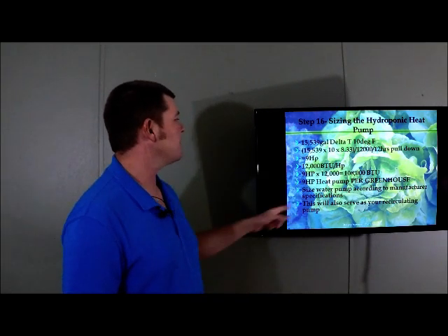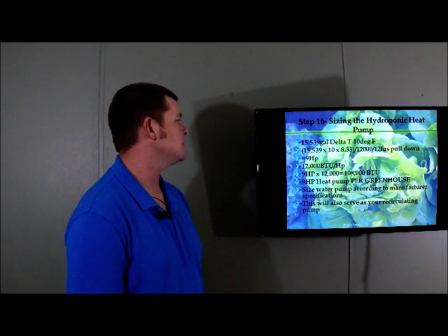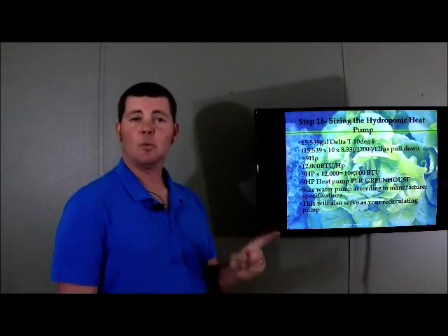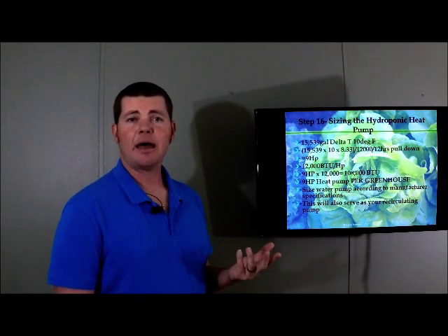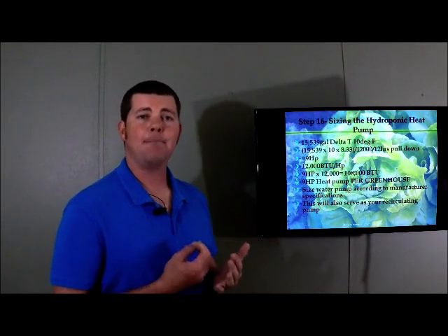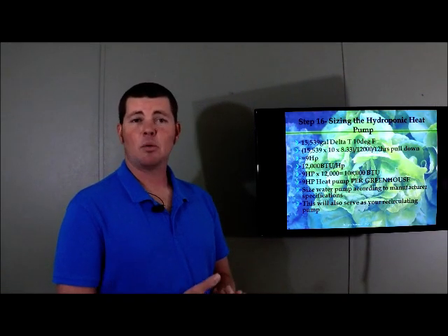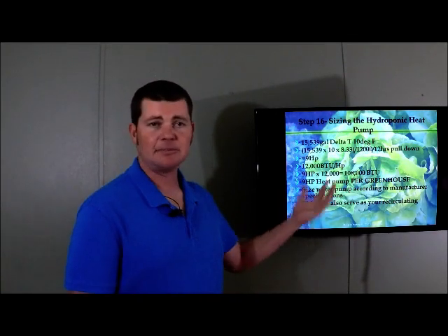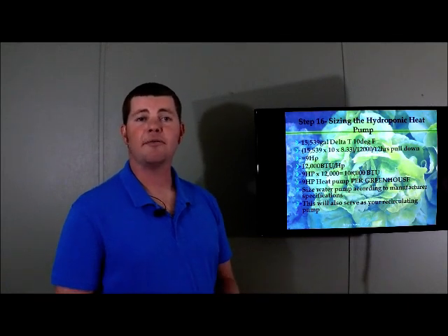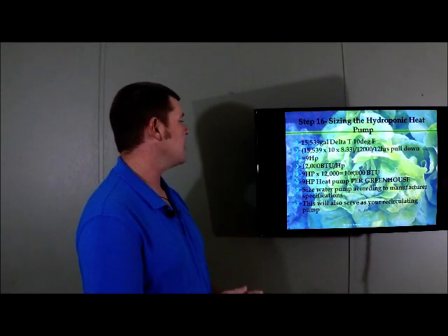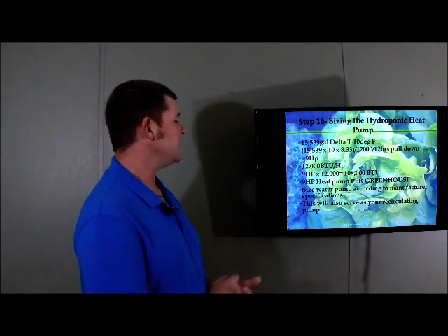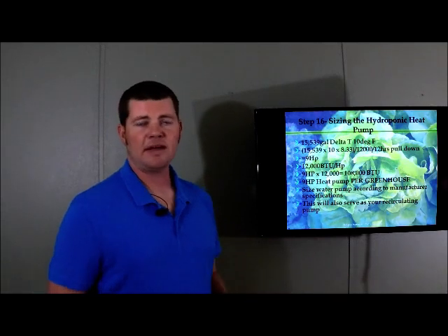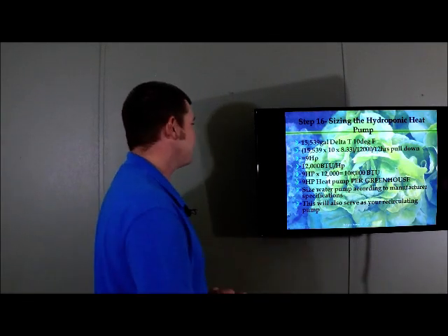So multiply that by 12,000 BTUs and we get 108,000 BTUs. A 9 horsepower heat pump per greenhouse. We need 1 per greenhouse, okay? It sounds like a lot. It is a lot, but that is a very important control parameter to keep the water temperatures where you need them. If you were using NFT systems, that'd be a lot smaller. It's nowhere near as much water volume. So there are other factors that come into play, but in this design, we need 1 heat pump per greenhouse. Think of this as like a heater for your swimming pool. If you have 15 swimming pools, you need 15 heaters for them.